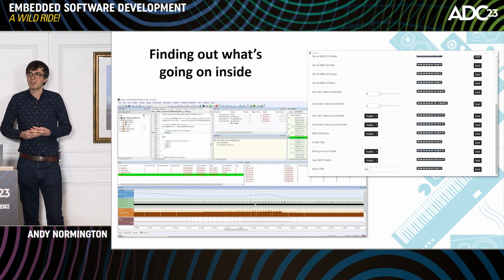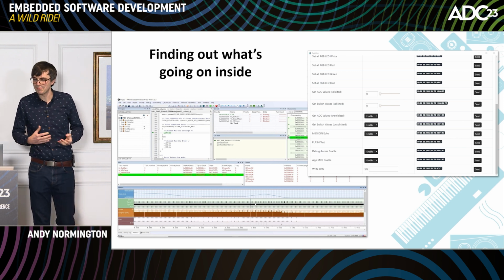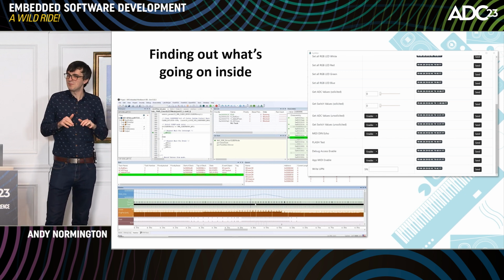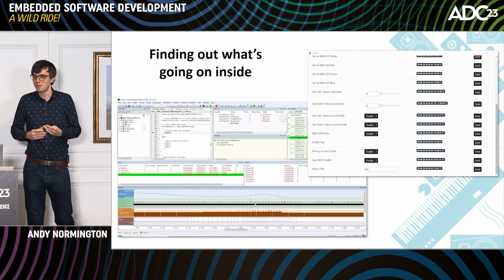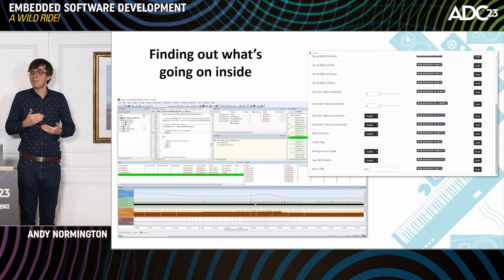In the past, we have tried to write some of those tests on the hardware and trigger a factory test mode, but what we tend to do now is to treat that as an API, set up simple get and set routines for the access that those teams need, provide a firmware update method, and then those teams have what they need to incrementally develop those tests.